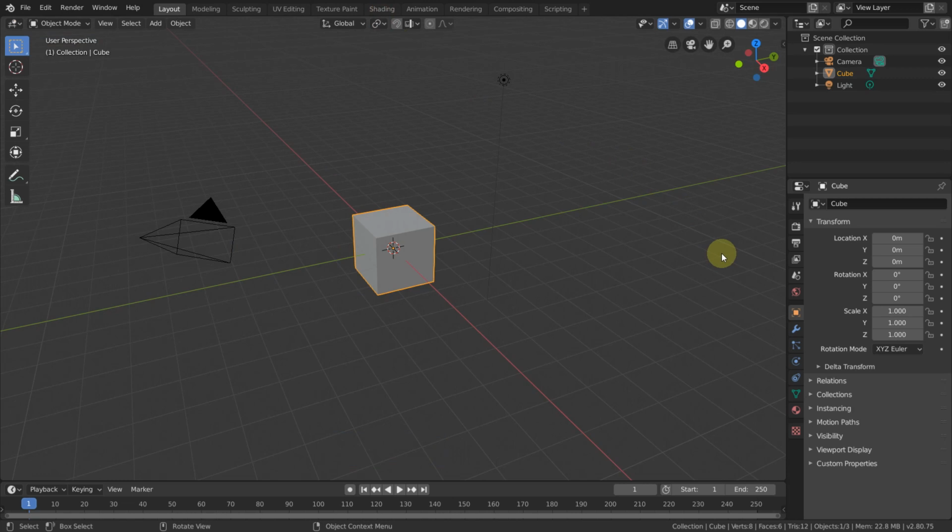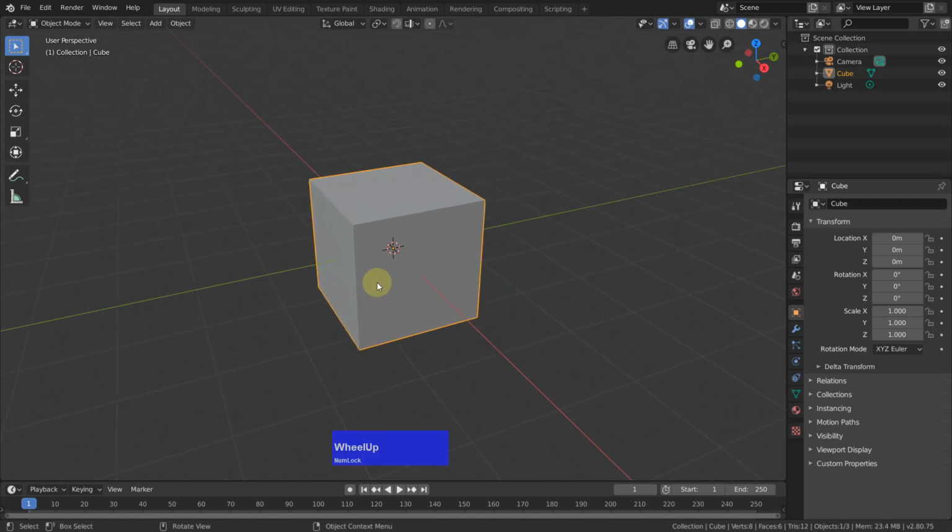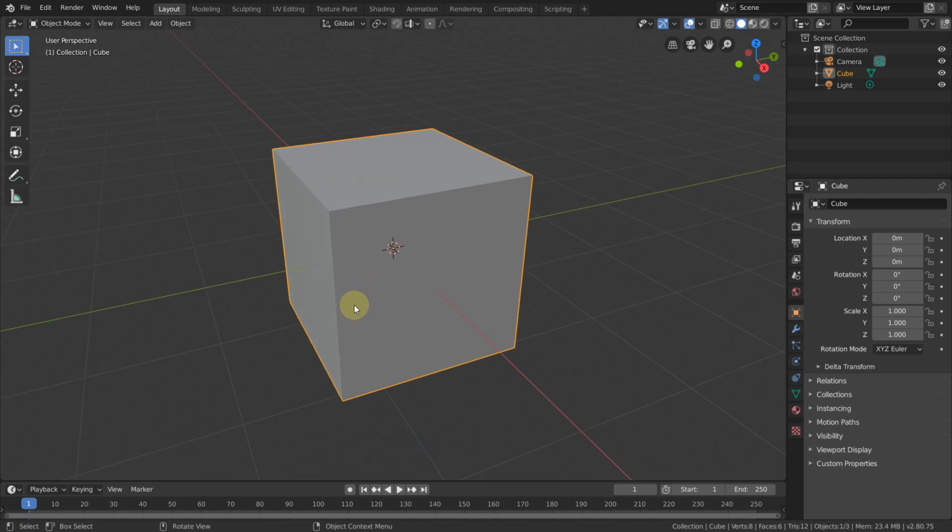One of the major differences, and this is the one which got me most, is in MODO, when nothing is selected, then everything is selected. In Blender, when nothing is selected, then there is nothing selected. So you have to select something in order to do something with it. Then the second thing is, in Blender, the axes X and Y are the horizontal ones, Z is the vertical one, and in MODO it's X and Z for horizontal and Y in vertical, which I think do not have many 3D packages.